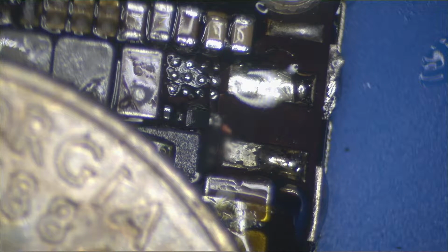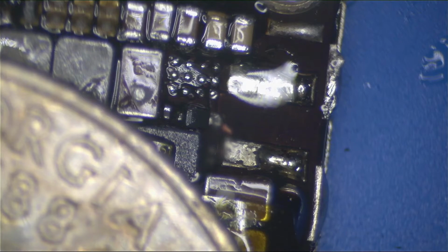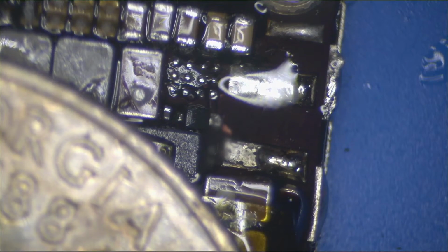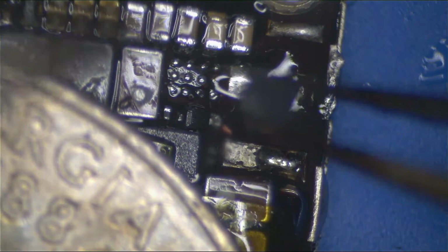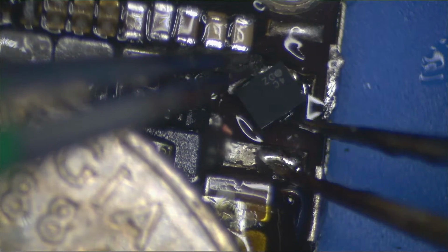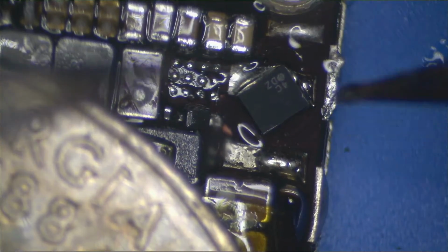And so I'm going to start out with just tacking the driver down. What I'm going to do is actually use my hot air to gently melt the pads on the coil so that the solder flows pretty evenly. And while that's happening, I'm going to have the driver in place, like you can see here. A1 is in the top right corner. You got to remember that.